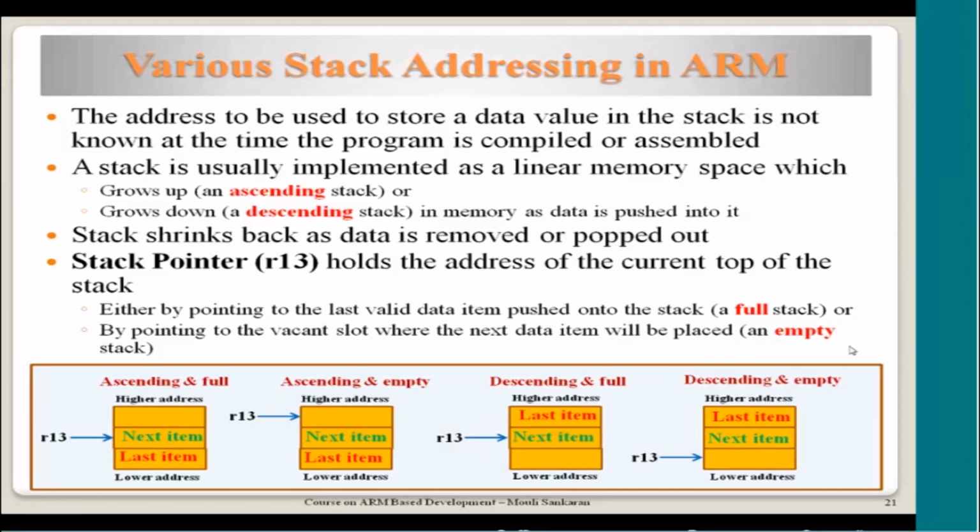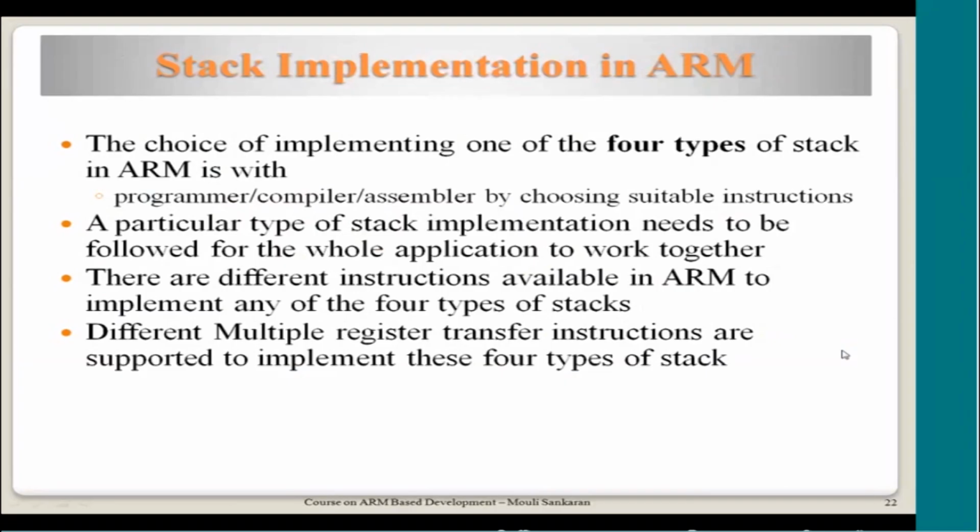Now let us see who decides which type of stack to be used. In ARM, it is decided by the programmer or assembler by choosing a suitable instruction. But the thing is, once we decide on a particular implementation for the whole application, it should be the same. We cannot use one instruction which assumes empty and descending, and then while taking the data out, use an instruction which is meant for ascending and full.